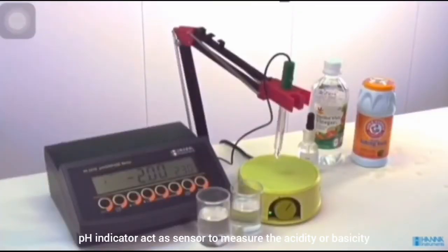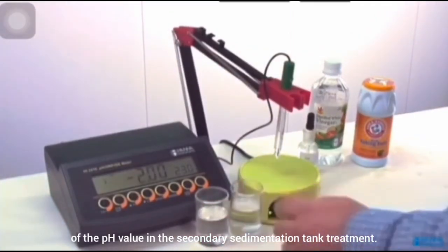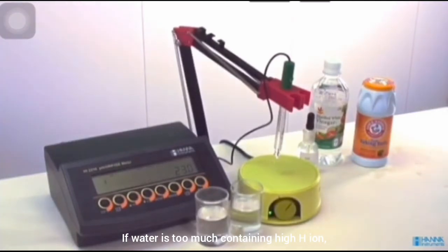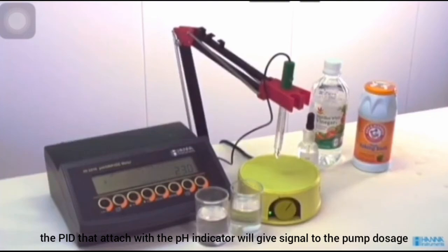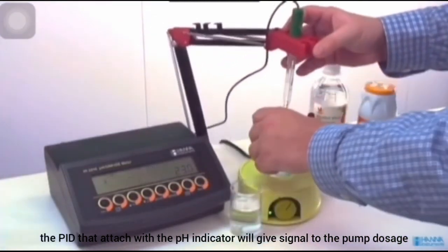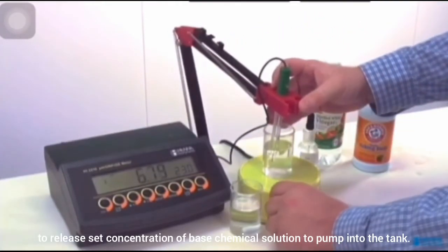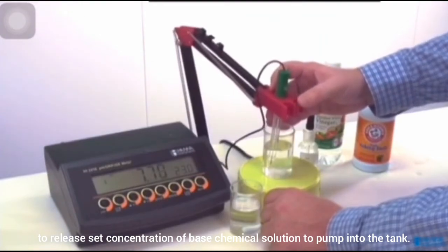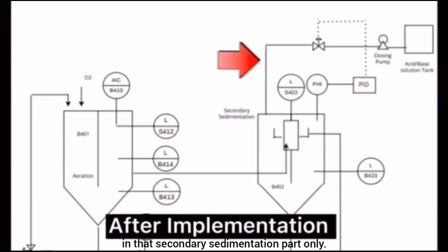The pH indicator acts as a sensor to measure the acidity or basicity, the pH value, in the secondary sedimentation tank. If the water contains too many hydrogen ions, the proportional integral derivative controller attached to the pH indicator will give a signal to the dosing pump to release a set concentration of base chemical solution into the tank. So the treatment process only involves the secondary sedimentation part.